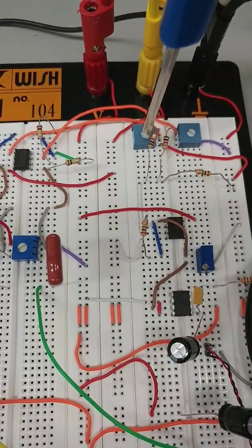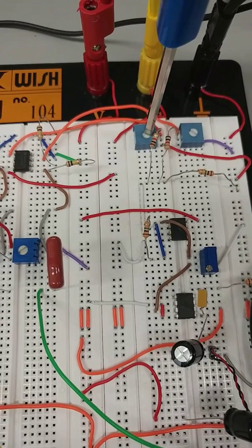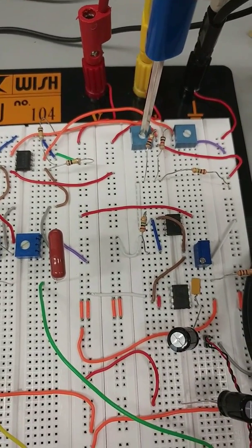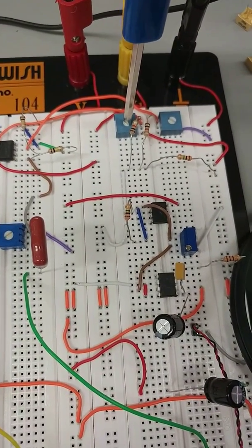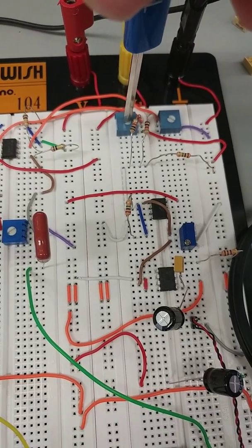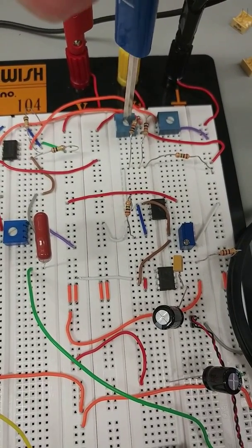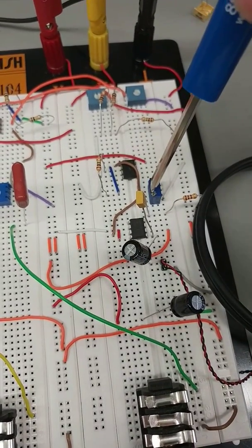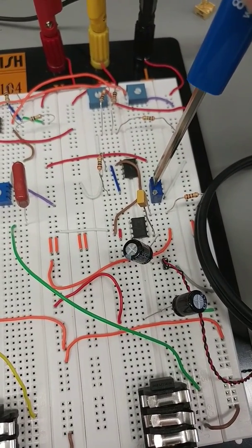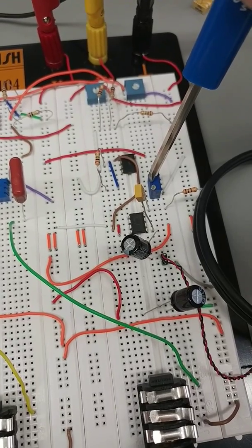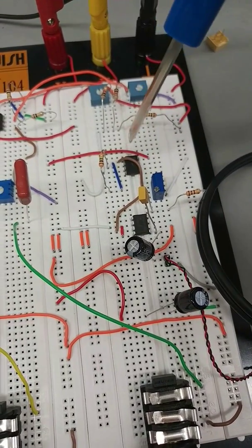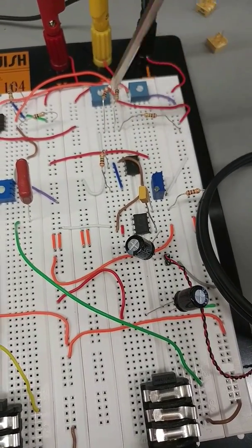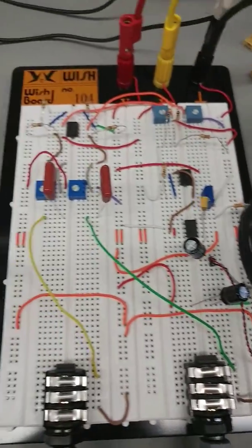And over here in the mixer section, we have this one, which is fully open for the electric guitar solo, and as I reduce it, it kind of disappears into the background. And then this 10K is basically a volume knob for the entire system, reducing or increasing the peak-to-peak input from the mixing channel, which is the second channel, which is up here.